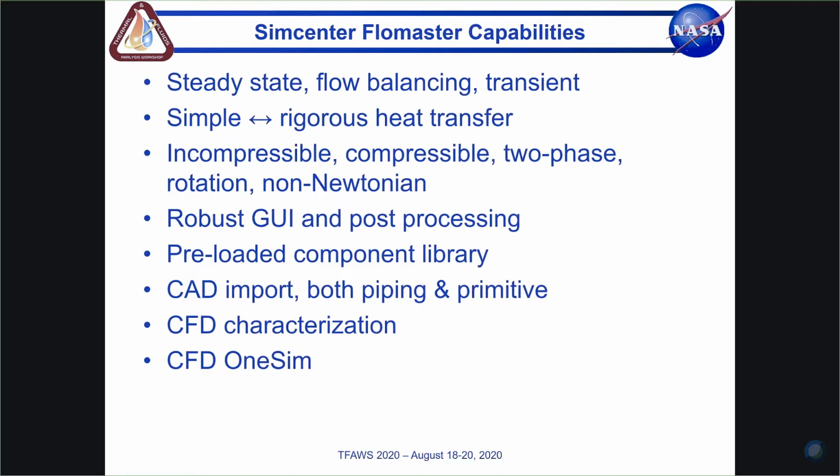In terms of heat transfer, we go anywhere from no heat transfer to simplified heat transfer all the way to rigorous heat transfer with conduction, convection, and radiation models. In terms of fluid properties, we can handle incompressible flow, compressible gases, two-phase flow with refrigerants or things like steam water. We can handle rotation in the context of turbo machinery, primarily secondary flow capability. That's flow moving in and out of rotating cavities inside maybe a gas turbine engine or inside a turbo pump. And we also can handle non-Newtonian flow as well.